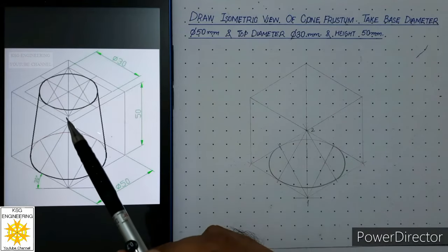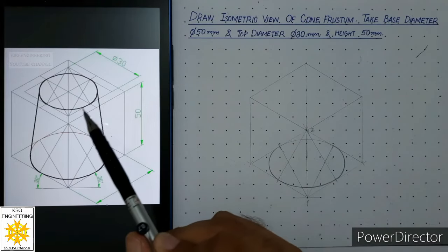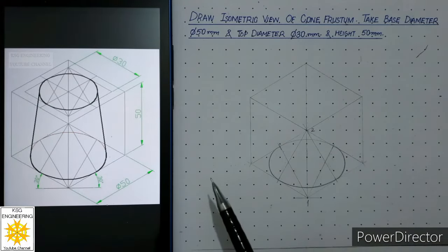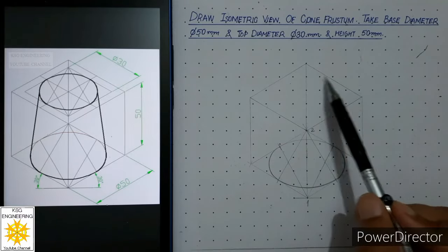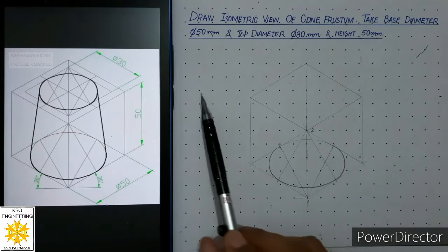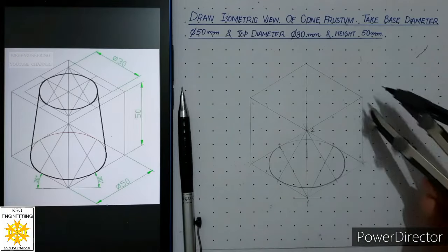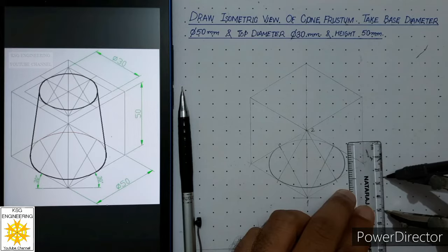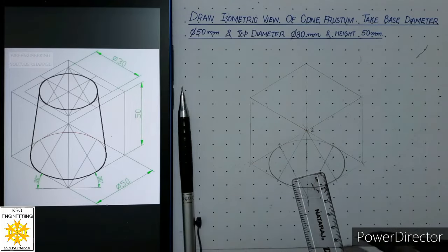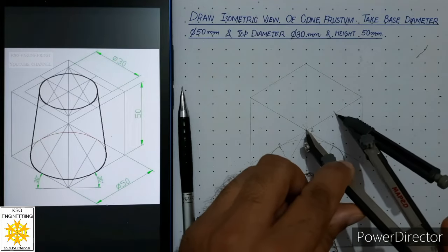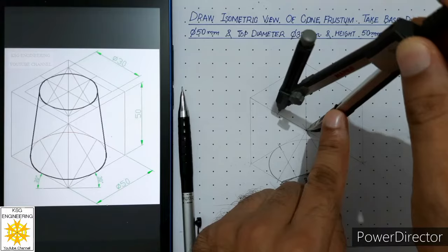So next step is we should create or we should draw a box of 30 millimeters inside this box of 50 millimeters. So for that, what we need to do? We need to mark the midpoints of these 4 sides first in order to draw 2 center lines. Now we know this side is of 50, so let us open compass to 25 again. Place your compass at this point and cut this length to 25. Similarly on other side, 25.